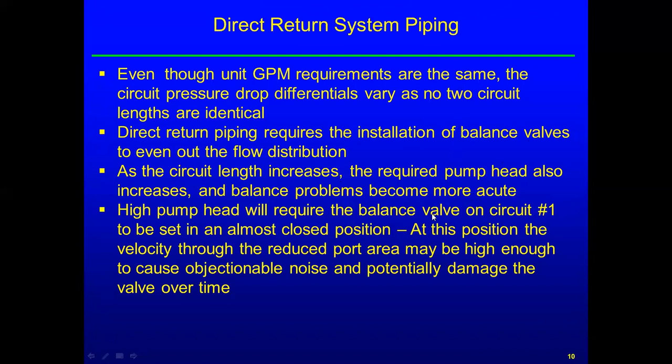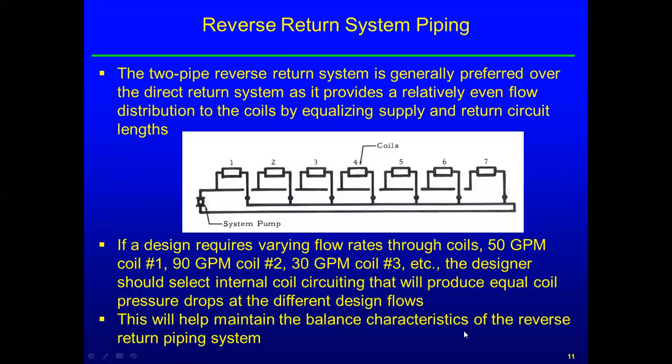So it's a problem. High pump head will require the balance valve on circuit number 1 to be almost closed. At this position, velocity through the reduced port area may be high enough to cause noise and damage the valve pretty quickly.